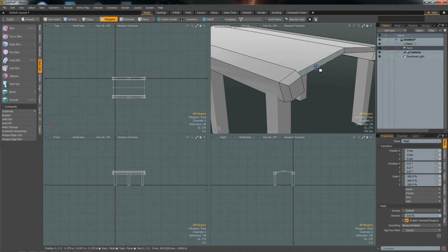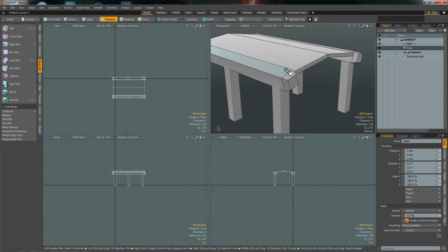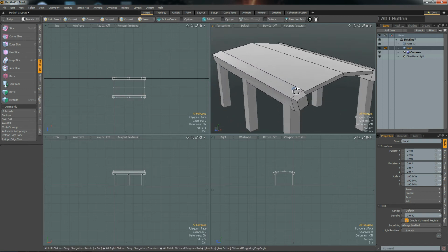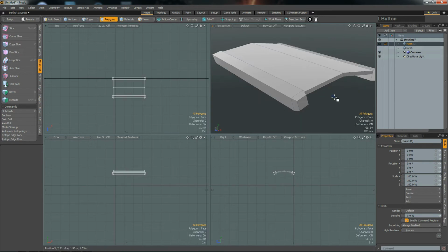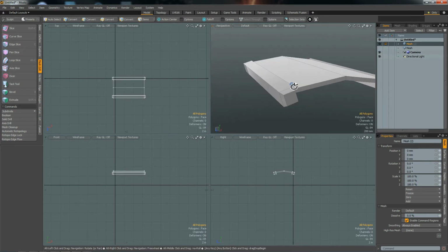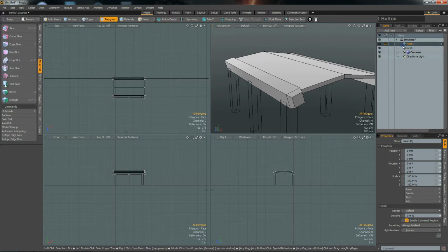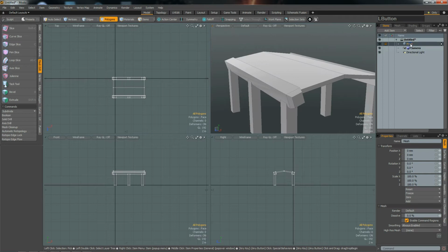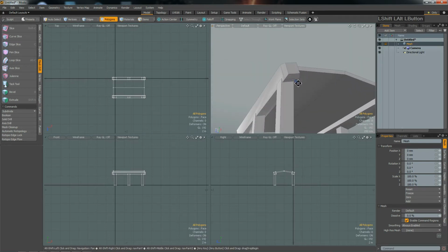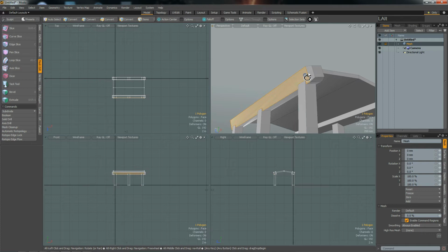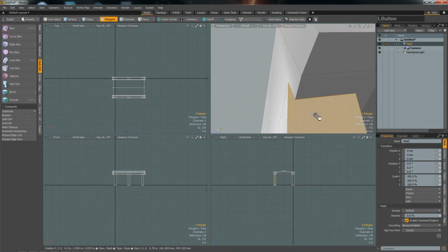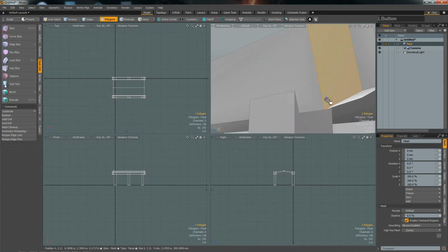That's because our original mesh, which was just the roof, is now overlaid over our original. Because when Modo does a Boolean operation, it will keep the original mesh there. So our original roof is still there. We could still do stuff with it, but we don't need it any longer, so we're removing it. And here we have our mesh with the appropriate cut out edges.